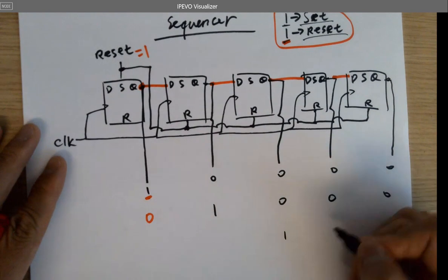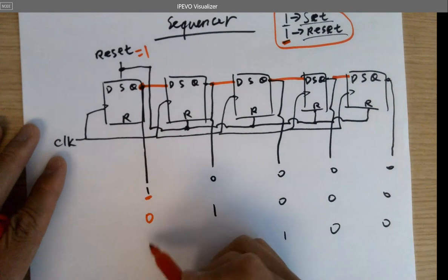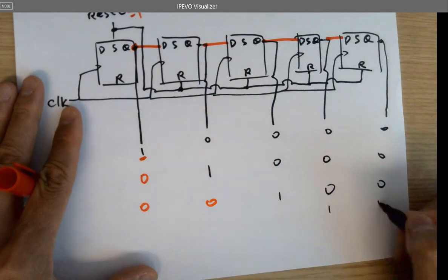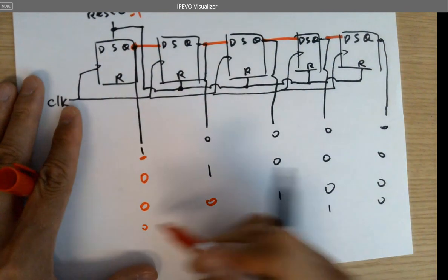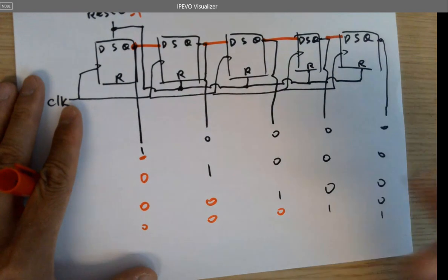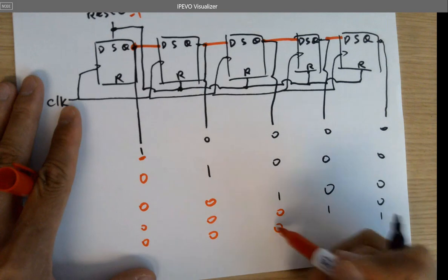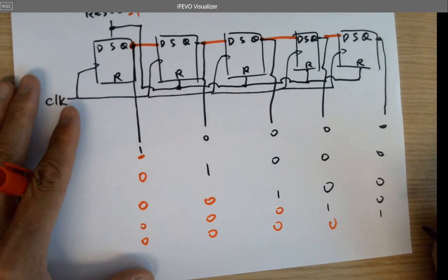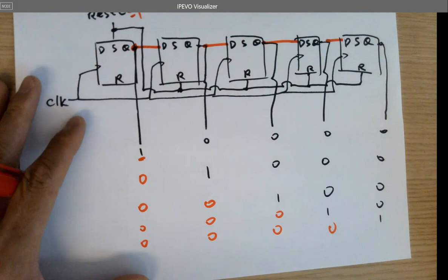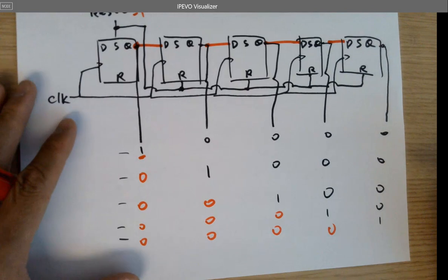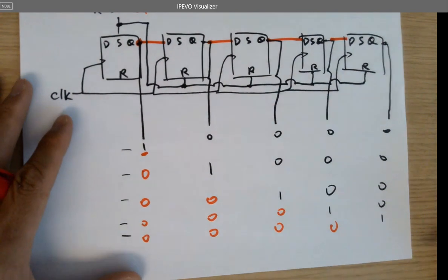And the next, I need this. I need 2 zeros in the front, right? And then I need this. I need 3 zeros. And eventually I need this. One more step actually. Do I need one more step? No, I don't. That's the final step. 5 cycles. 1, 2, 3, 4, 5 for 4-bit ADC. That's all the cycles I need.